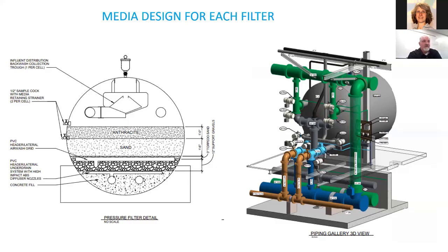Currently, we are under mandate from Eagle, because of the size of our system in the North Campus area, to monitor 10 sites spread out over the system to fairly represent the system. We take the bacteriological sample from each of these 10 sites twice a month, every 2 weeks.